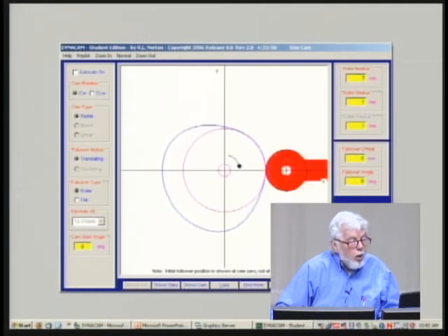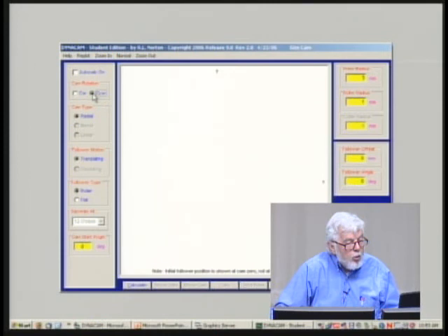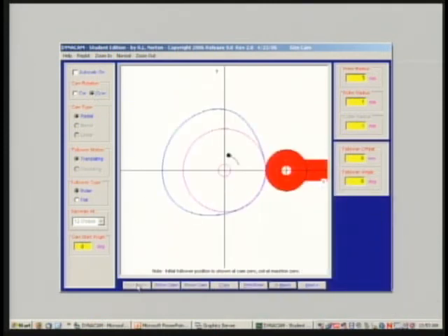So if we hit the Calculate button, for the chosen radius of curvature, which I had previously put in as a 3, we see a pretty acceptable cam. Now, the cam is rotating here clockwise. I can switch that to counterclockwise with this button over here and recalculate if I wish. That would depend upon your particular situation. The cam is going counterclockwise. That's the same as if the roller were going clockwise around the cam, a process called inversion.